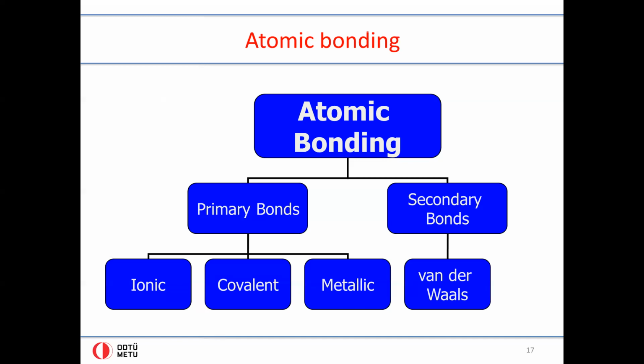And if you try to break this, and the bonds inside the polymer, inside the glue, are stronger than the bonds between the glue and the skin atoms on your finger, then instead of the glue breaking, part of your skin will break and you will feel tremendous pain. So this is all dependent on the strength of the bonds that you need to break. And if you have primary bonds at play, the secondary ones are not tremendously important.